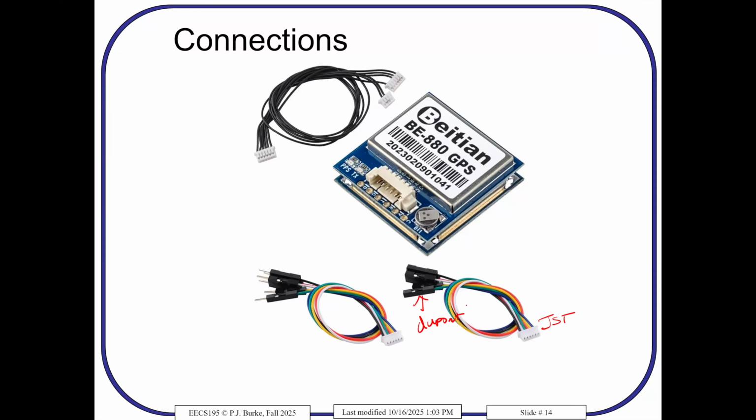I recommend depinning the 1x1s and making a 1x6. Otherwise, every time you plug the GPS into the flight controller, you're going to have to figure out where each of the 6 wires goes. And if you remove the GPS to do some other repair in your drone and you need to plug it back in, you're going to have to go back and look at the wiring diagram to figure out where every one of the 6 wires goes. So depin the 1x1s, put them in a 1x6, then it's much easier to plug it in each time, and label it.